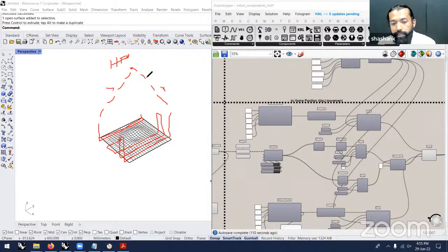One thing that I need to ensure is that once I start to move, I will reach this position first. The speed might be a little faster here, and it might be slower here, and start to slow down as per the specification. What I'd ideally like to do is, once it reaches a certain position, turn my spindle on, or turn my signals on, or turn the tool on. Once this is set, I want to trigger that event of setting the tool on, and I can program that within the Grasshopper component as well.